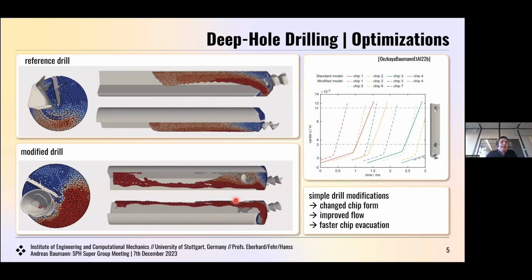On the right-hand side, you see the simulation from before. We have the elastic chip before placed here within the evacuation fluid, and we have the fluid flow coming from the bottom, and of course, our artificial barrier on the right. And we see that the fluid flow catches the chip, transports it along, and also by looking onto this elastic deformation, we see that once the chip is catched by the fluid flow, we don't see much deformation of the chip itself.